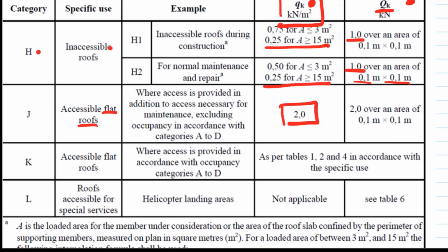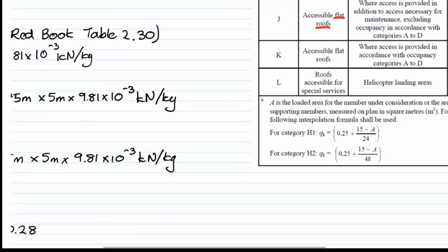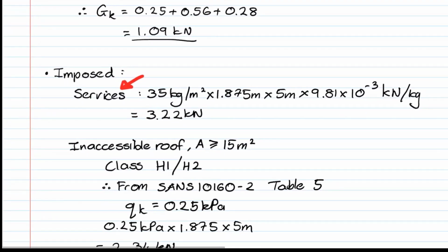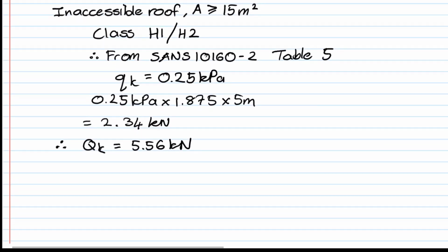So for those specific requirements, we increased it to 5 in general because of safety implications and knowing that 20 years from now someone might put something heavy on that concrete roof when they have a new electrical piece of equipment or so. So keep these things in the back of your mind. We have good code guidelines, but sometimes code guidelines cannot account for what your client will do in real life, and you should try see what might be a realistic scenario that could occur.